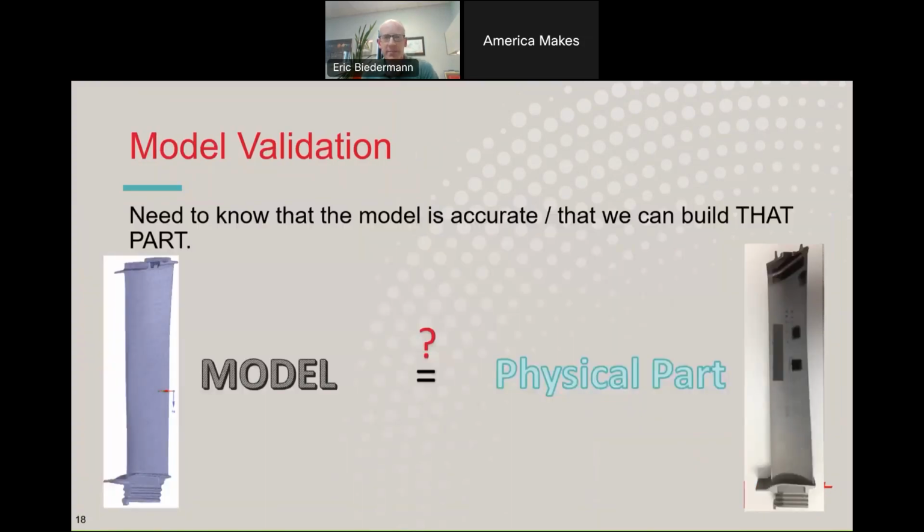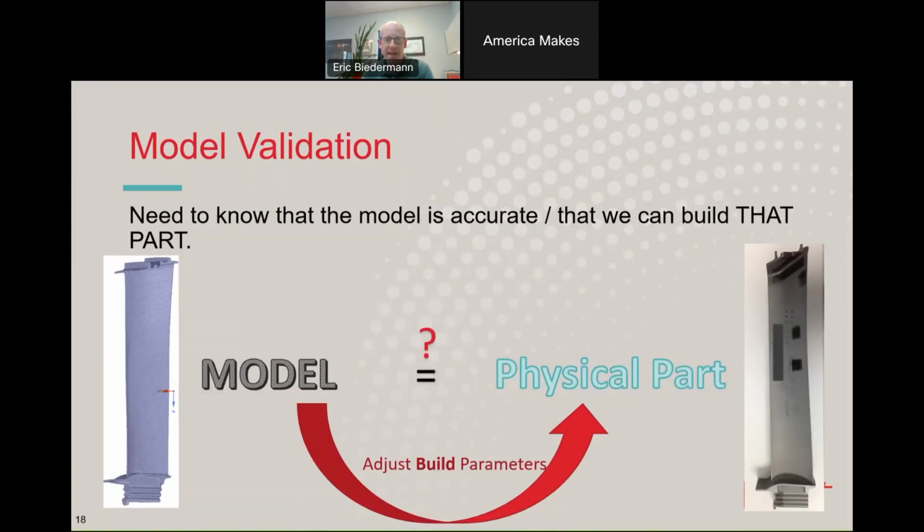Now, going from basic pass or fail testing and other process control measures to some other things we can do with PCRT, we start with operations with models. Additive manufacturing is fundamentally a model-based process. We almost always begin with a 3D solid model, or in some cases, we begin with a physical part that we want to reverse engineer into something we can make additively, and that usually involves scanning it into a 3D solid model. What we can do with the resonance information, that quantitative fingerprint of the part's material state, is use it to either increase the accuracy of our model or tune our build parameters to better reflect our original model